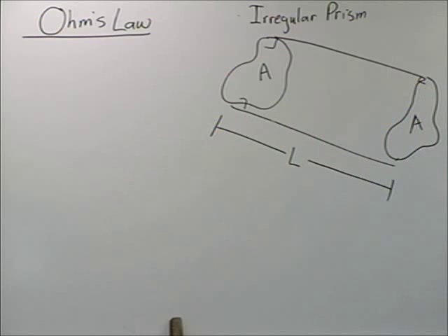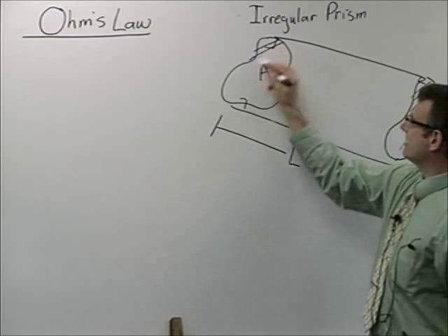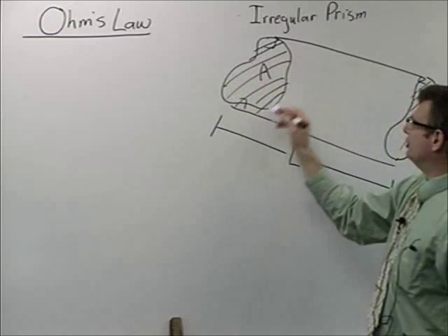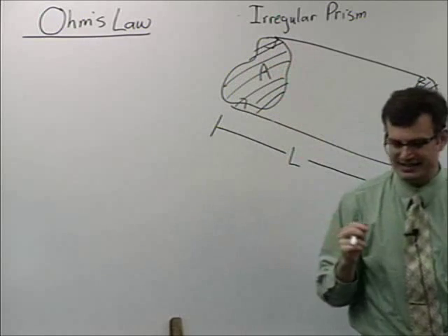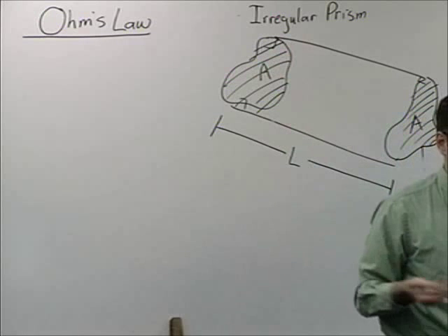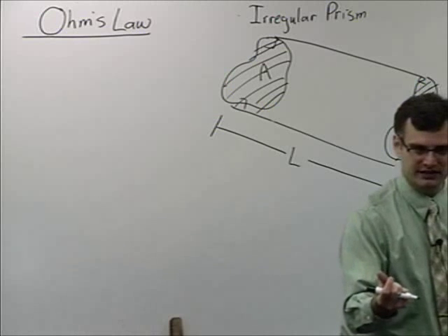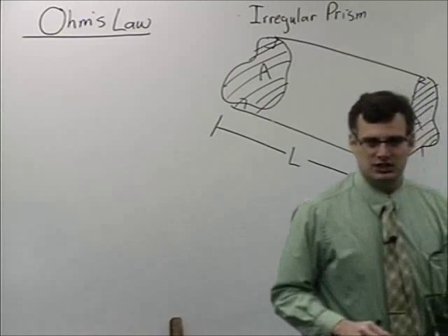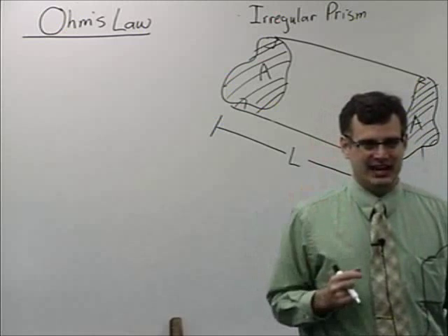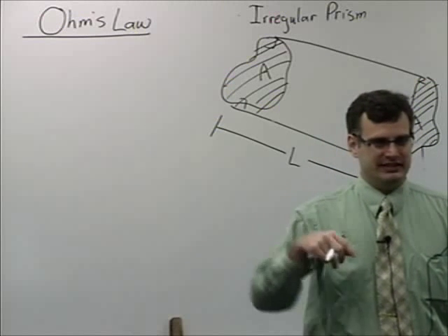And what we're also going to do is metallize the junctions here. That's nice because whenever you metallize something, you pretty much assure that the entire surface is at the same potential. Why is that? Because good conductors don't allow E fields inside of them. As soon as you impress an E field, the charges stretch out and instantly counteract it, so the E field is always 0.